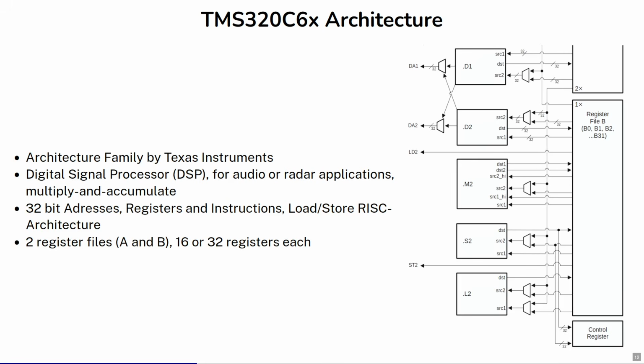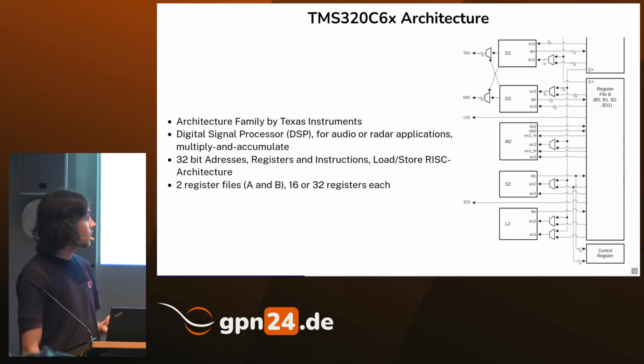It's a load store architecture, and we have 2 register files of either 16 or 32 registers. In the base version it's 16, and in later updates they increased it to 31 registers. There are 8 functional units, 4 of them are shown in the bottom, as well as the wires they connect. They have dedicated usage.